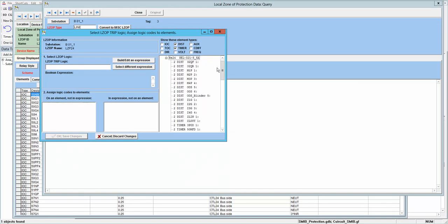the different elements of the relay here, the distance elements, and different timers for the elements of the relay. So you can add overcurrent, directional, or auxiliary elements for that, but right now I wanna just work with the distance elements and the timer settings for just zone 1 and zone 2.